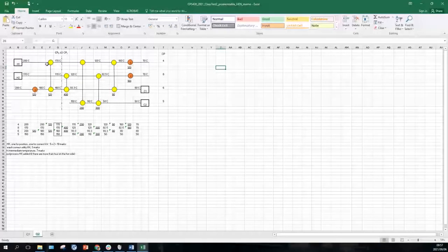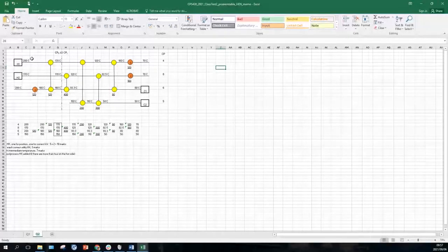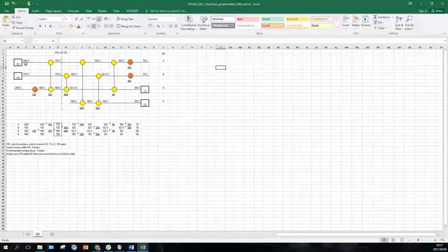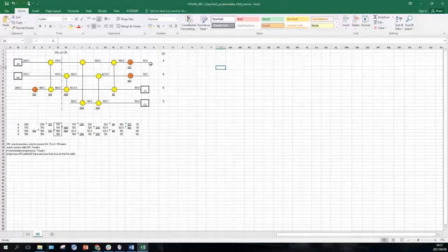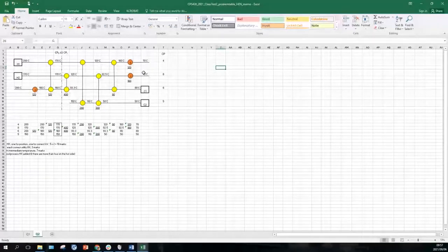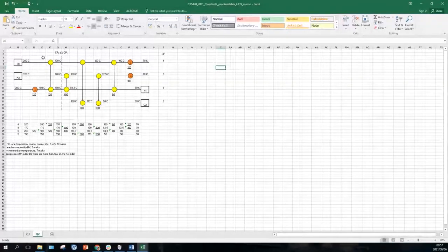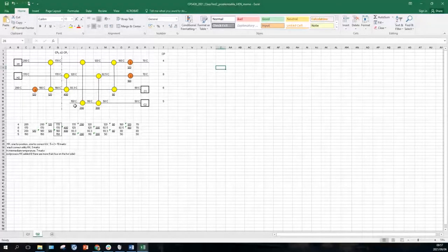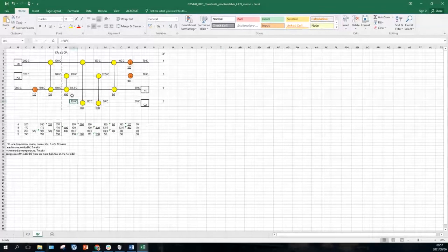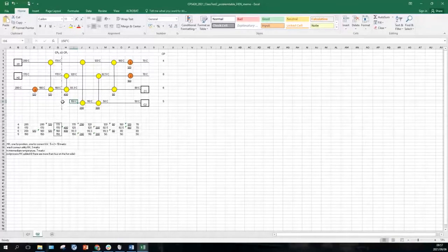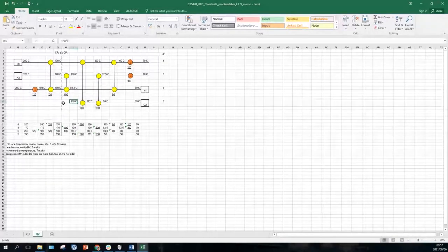So we put in all of our H1, H2, C1, C2, and we draw the horizontal lines, and the temperatures, we know where they start and where they end. So we can put in these 270 degrees C, we can put in the 200, 170. C2 doesn't get to the cold pinch temperature, which is 160. So you only draw it until before this to make sure it's all correct.